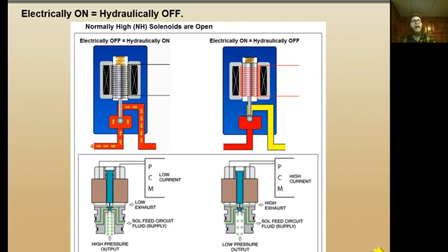Two, can I take off from a stop? Let's say we have a 6-speed transmission and it's stuck in 6th gear. It's going to be really, really hard to take off from a stop, and that's going to create a lot of heat inside the torque converter, because that torque converter is going to need to allow a lot of overrunning to happen inside of it. So a lot of heat would be produced, which could damage the fluid and then potentially damage the internals of the transmission more than maybe they already are.